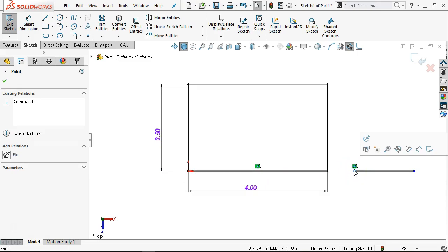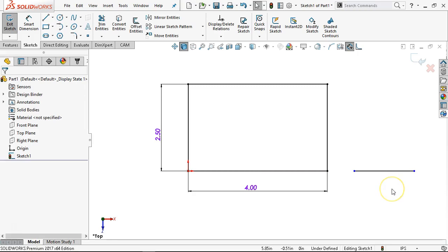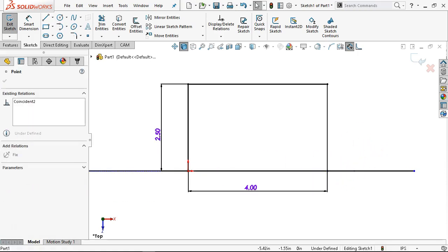So we can equate those as if for some reason collinear may not work, then I would be looking to see if the lines were not parallel or were not capable of becoming parallel. Otherwise, I would go to the endpoint and the line and pick the coincidence. All right, so 6 of one, half dozen of the other. It's, again, what you see or what you recognize. Collinear from the design perspective, most of the time makes more sense. I'm making those two objects share the same line infinitely. All right, so if I stretch this out, I zoomed way out and I stretched that out. It doesn't matter how big it gets, it's going to stay collinear.